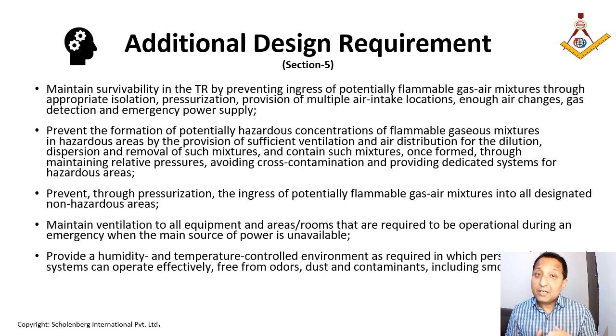There are certain additional design requirements which are stated in the standard. Let's see what those requirements are. First is to maintain survivability in the TR by preventing ingress of potentially flammable gas mixtures through appropriate isolation, pressurization, and provision of multiple air intake locations and enough air changes, gas detection, and emergency power supply. Well, what does it mean? Okay, when we read it, it looks very heavy, but in reality,